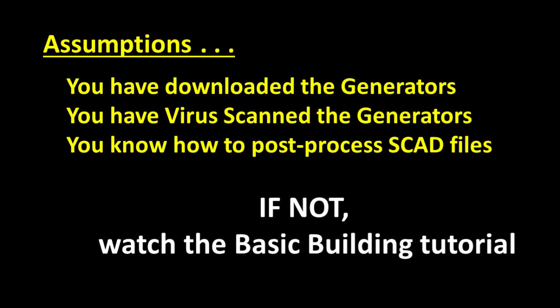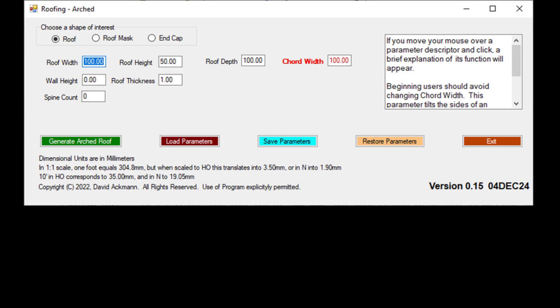Before discussing the generator, we need to make a few assumptions. We will assume that you have successfully downloaded the generator's zip file, extracted the executables, virus scanned them, and launched the arch roofing generator. We will also assume you have learned how to post-process the SCAD files through the OpenSCAD program to create stereo lithography files. If either of these assumptions is not correct, please watch the tutorial on creating a basic building where these concepts are introduced. As a reminder, the default values of all parameters represent good starting values, and if you are new to a generator, I recommend starting out by just clicking on the green Generate button to see how things work.